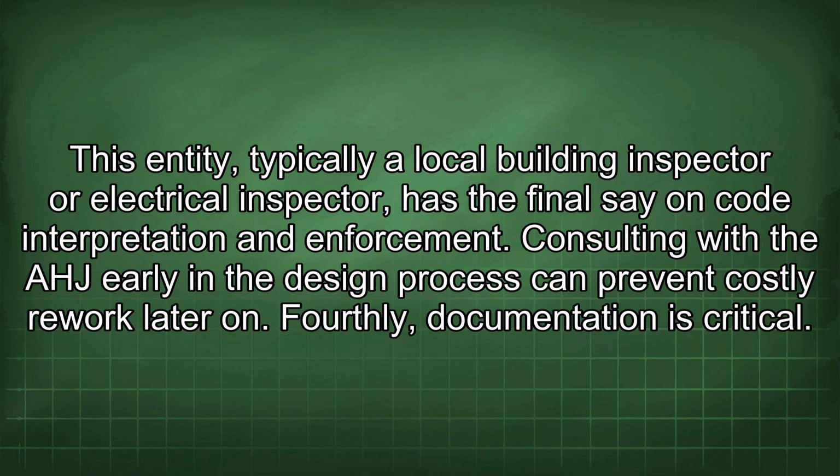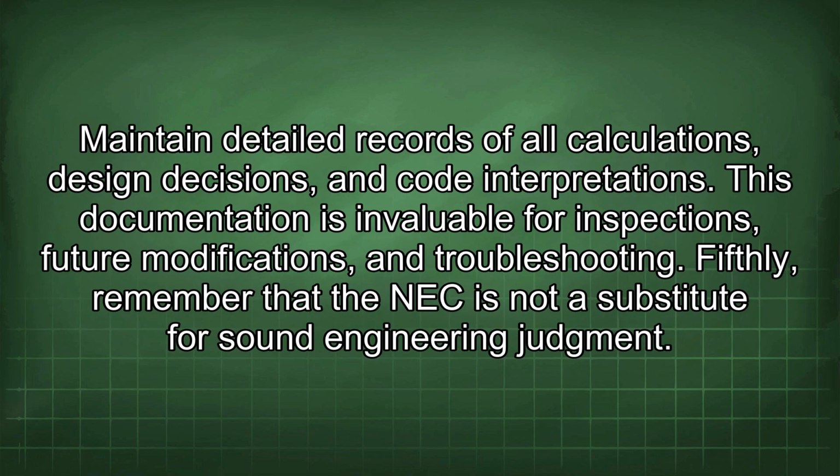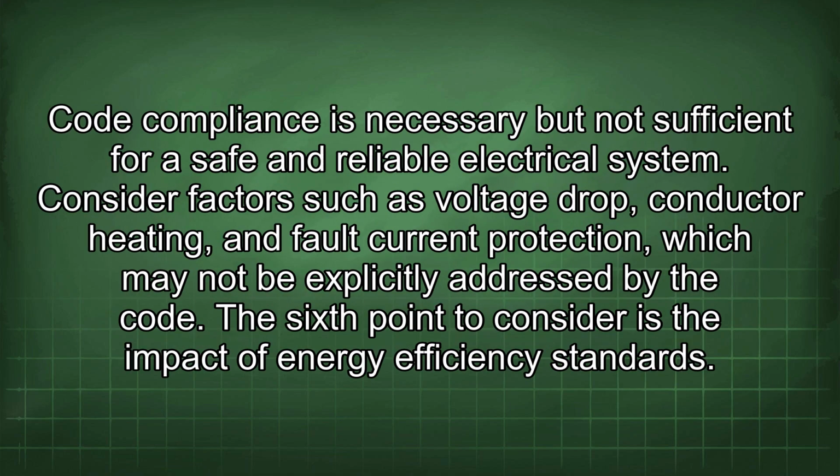Fourthly, documentation is critical. Maintain detailed records of all calculations, design decisions, and code interpretations. This documentation is invaluable for inspections, future modifications, and troubleshooting. Fifthly, remember that the NEC is not a substitute for sound engineering judgment. Code compliance is necessary but not sufficient for a safe and reliable electrical system.